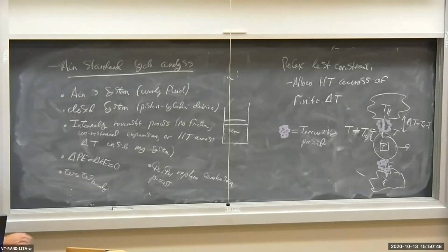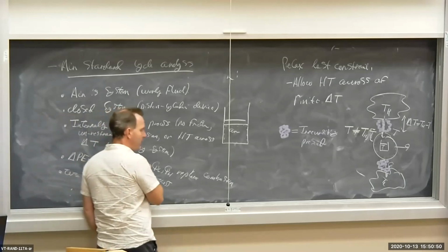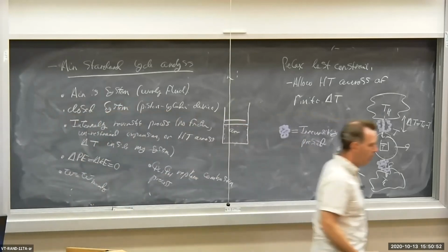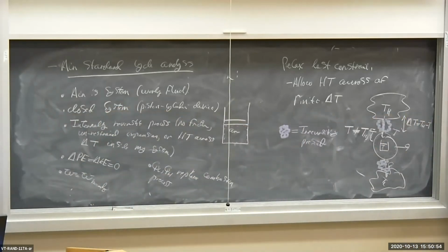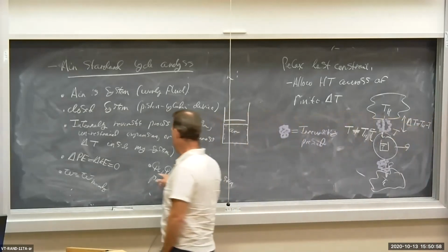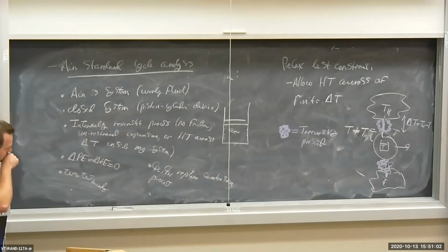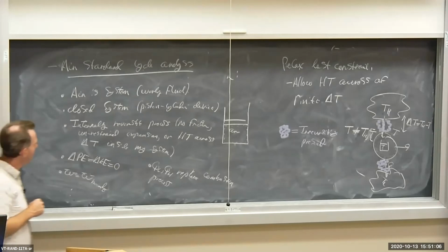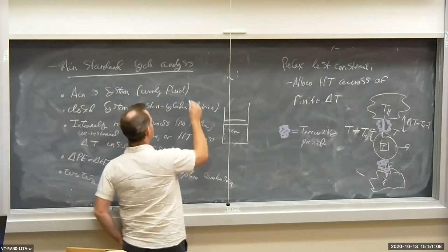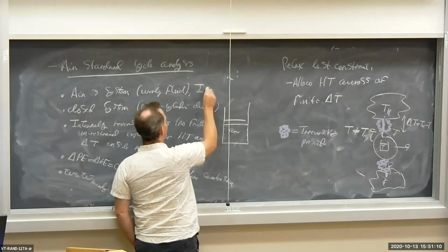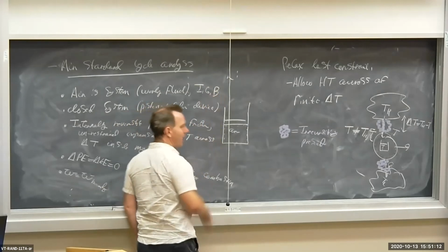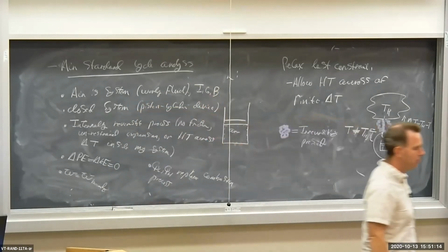So we're replacing the combustion process and the replacement of burnt air-fuel mixture with simple heat transfers, QL and QH. Also, I didn't put it down here, but I'm going to write right here, ideal gas behavior, IGB. We're going to assume ideal gas behavior for the working fluid.